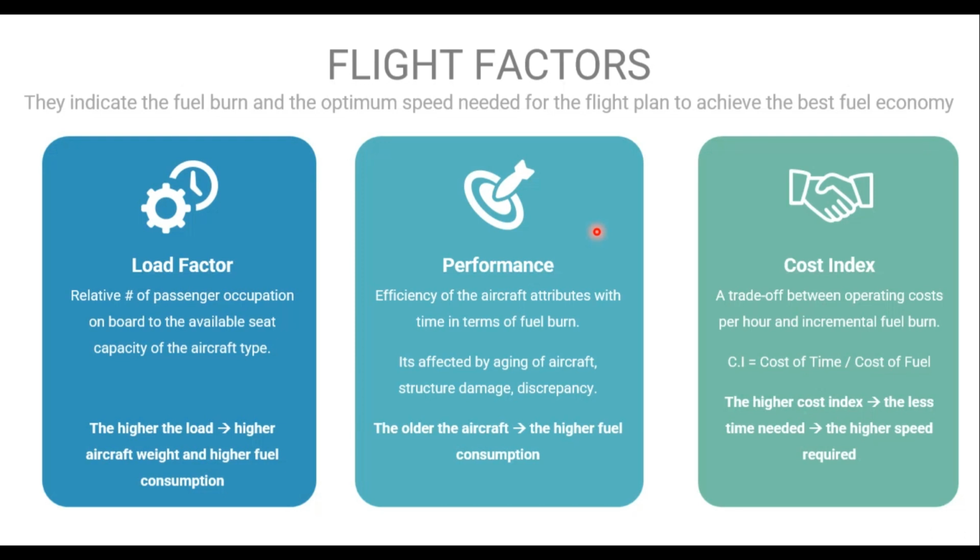The performance factor is calculated based on the age of the aircraft and the dry operating weight of the aircraft and so many other factors, how many cycles, how many hours, the deactivated systems on the aircraft, the extras on the aircraft, a lot of factors. Eventually, the people in the research department in flight operations come up with what we call the performance factor, and we put it in for fuel management.